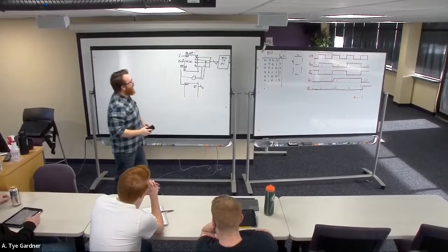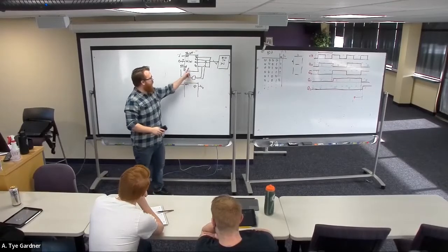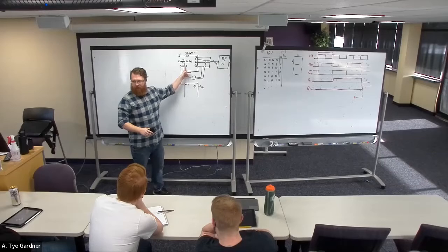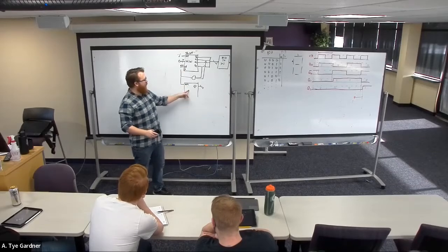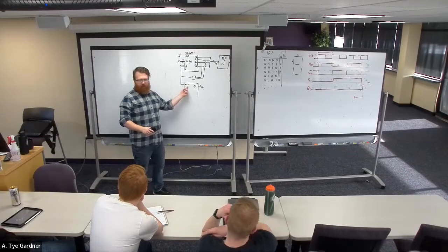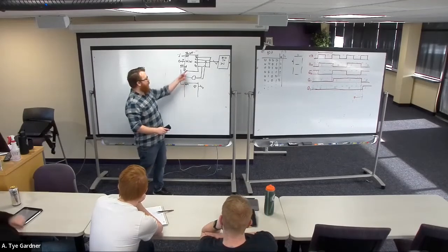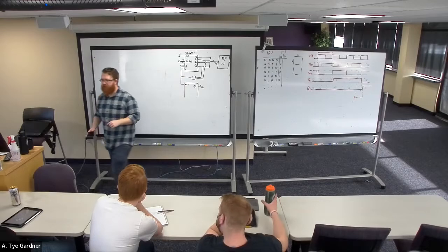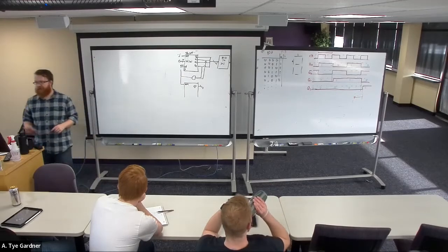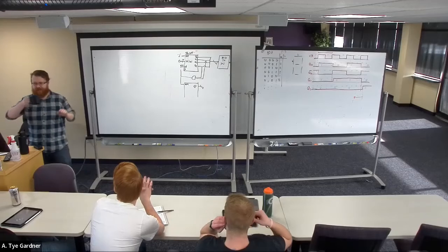And I just want to make a note, actually, as I think about this more. I designed this reset assuming an asynchronous load. I don't think the dual setup would actually work with the asynchronous load because the enable would exist for such a short period of time that the other clock wouldn't see it. So I would probably redesign this to be a synchronous load in order for it to work. Just so you're aware, if you end up building one of these, be aware that I think it needs to be a synchronous load.